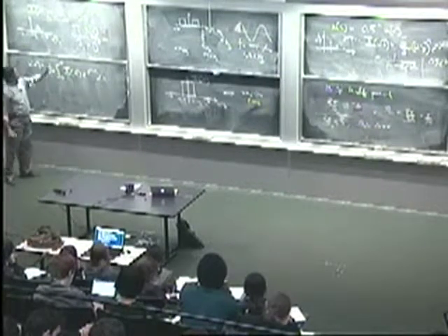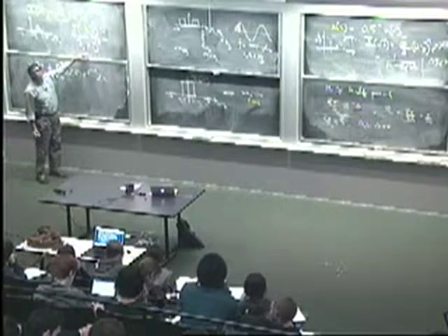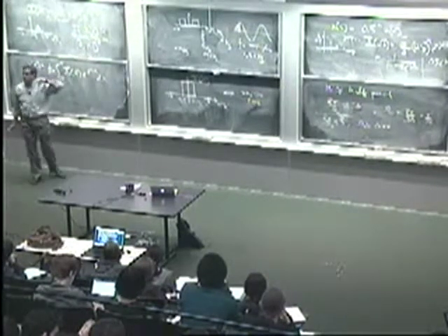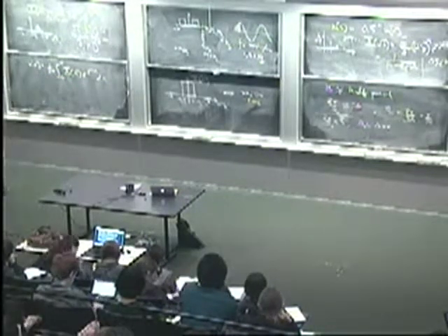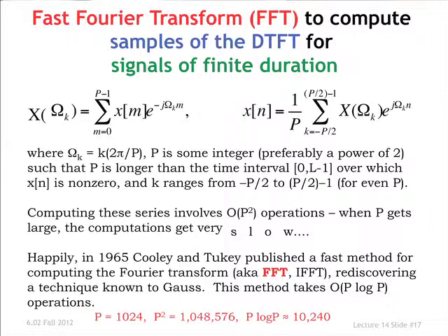What's interesting, though, is it turns out, and you might expect this, since your signal takes non-zero values only at p points, you only need p samples of the DTFT to get an exact reconstruction. And here is the formula. And the derivation is not hard. I've omitted it here. It's the same kind of idea that we used in the full case. But you can actually, using the values of the DTFT at these grid points, reconstruct the signal x of n. Okay? So, with these simplifications, you actually have a simple pair that gets you through the numerics.